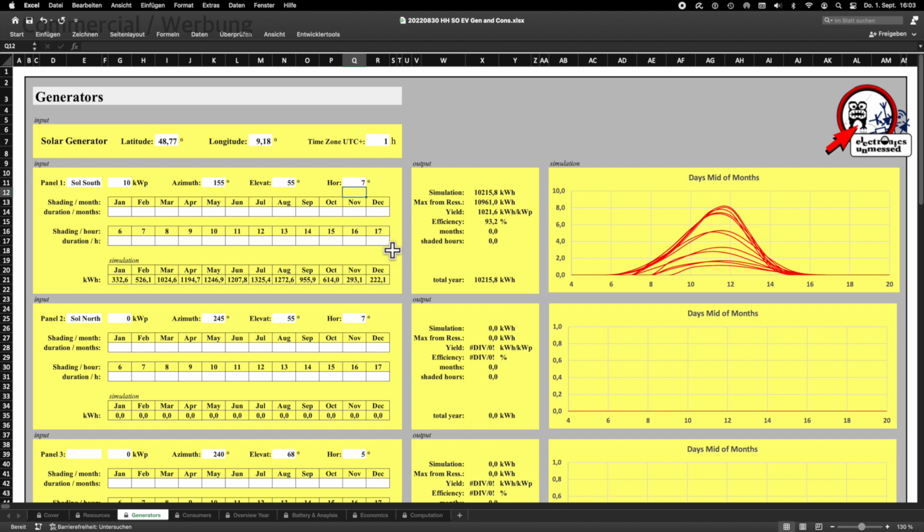For the rest of the year, the tree's shadow effect is only 10% because it has no leaves during that time. We can simulate this by inserting the value 1 for the months April to September, where the tree is carrying leaves. And for the rest of the year, we insert 0.1 corresponding to the 10% shading effect.